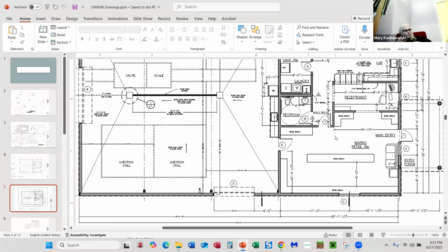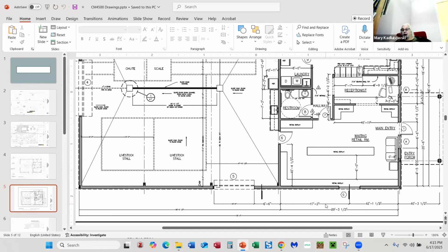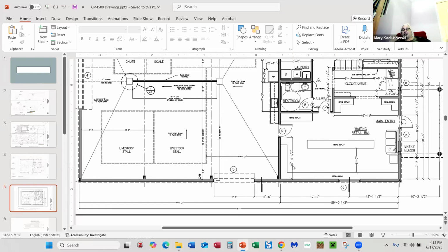Generally, your rule of thumb for a ceiling grid is every other tile in one direction and every 3 tiles in the other direction for 2 by 2 tiles. Does that make sense? So if this little spot here is 30 feet, you're going to have 15 tiles here, right? So if you go every other, you're going to need 7 lights in here. Is there going to be a drop ceiling? Yeah.